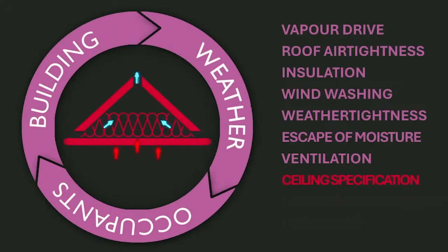If not carefully designed, the pressure drop between a ventilated loft, particularly if ventilated at the ridge only, can set up additional suction forces on the ceiling, drawing both heat and moisture from the habitable spaces below. Any changes to the ceiling assembly, for example adding downlighters, or in the longer term, maintenance to building services such as HVAC systems, may affect how this moisture can enter the roof space. The impact of any proposed alterations or maintenance work on the airtightness of the ceiling assembly should therefore be fully considered at the earliest possible stage.